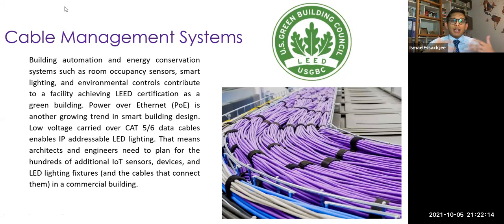But then you need to interconnect all these devices if you have maybe lights and so on. So for basically one technology, not technology, but an approach, you're using power over Ethernet. They use a lot of these data cables. So you need to know how to route all these cables ultimately. Wireless is good at some point, but you will need to wire these devices. So lots of devices in a building. In a house, it is manageable, but in a building, it's going to be huge. So we'll need to cater for cable trays and so on.